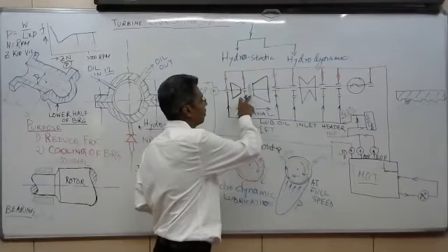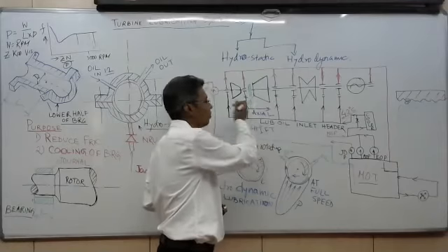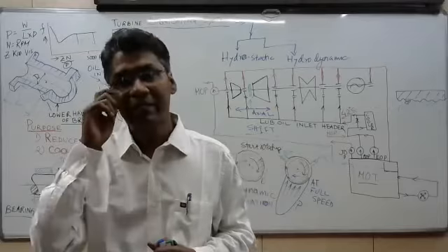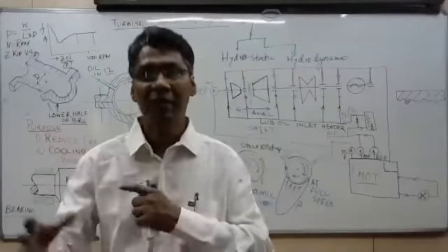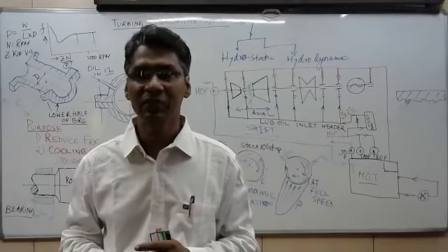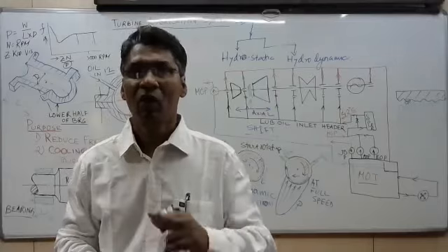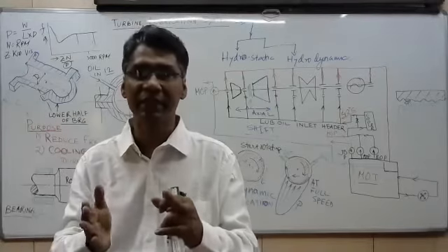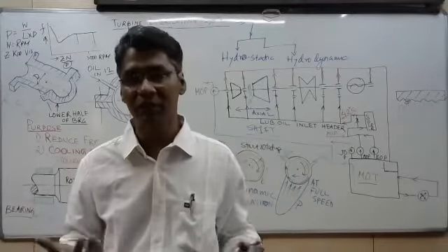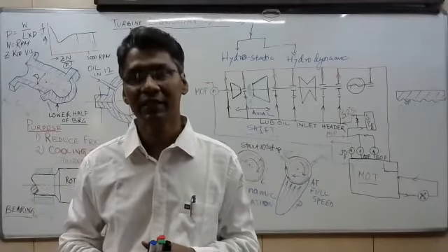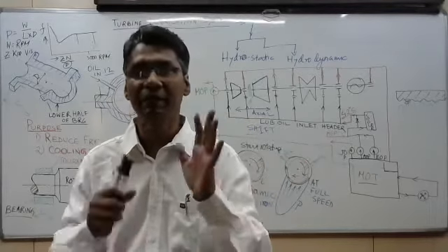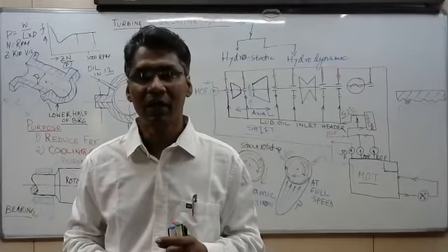Whether the arrow from this bearing is negative or positive depends upon your turbine. Axial shift takes place because of the turbine balancing system. It's related to the turbine balancing. If your turbine balancing is not proper, it will give a one-directional shift, and it may be that the sign is negative. That means the pressure is in the opposite direction. If we balance the other direction, it may be positive. So the balancing is to be checked for this. A little bit of negative doesn't matter. It may be positive or negative. It depends upon the balancing of the turbine.